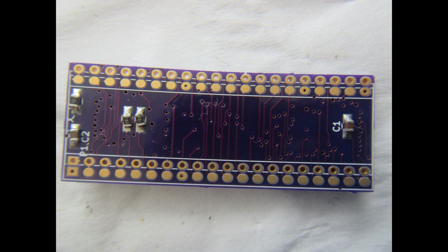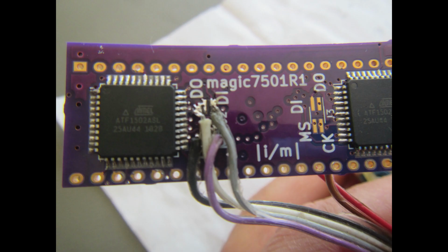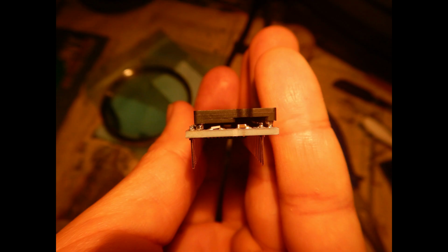40-pin SMD socket. At this point, I soldered the needed wires to the JTAG connections to program the two CPLDs. For details on my JTAG setup, you can watch the previous video of this series that's linked in the description. By the way, in this case, the JTAG headers do not follow any standard, but that allowed me to save some space and have an easier routing. After programming both the CPLDs, I soldered the socket and the pins.